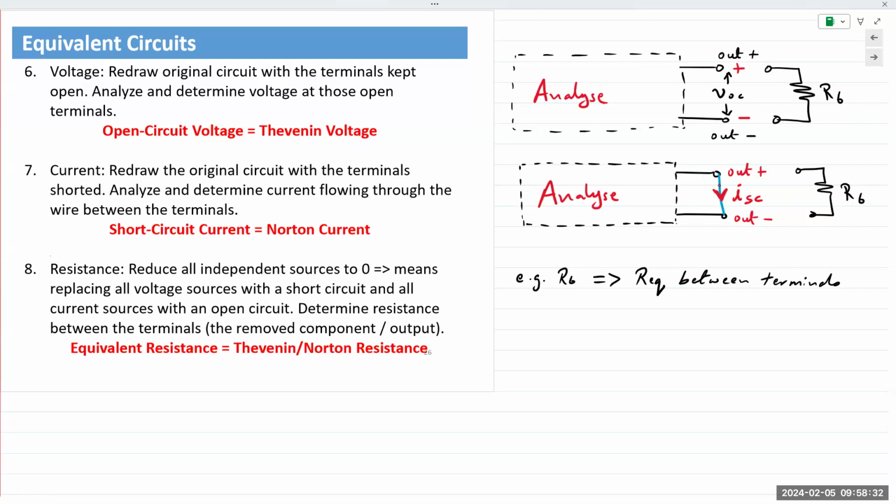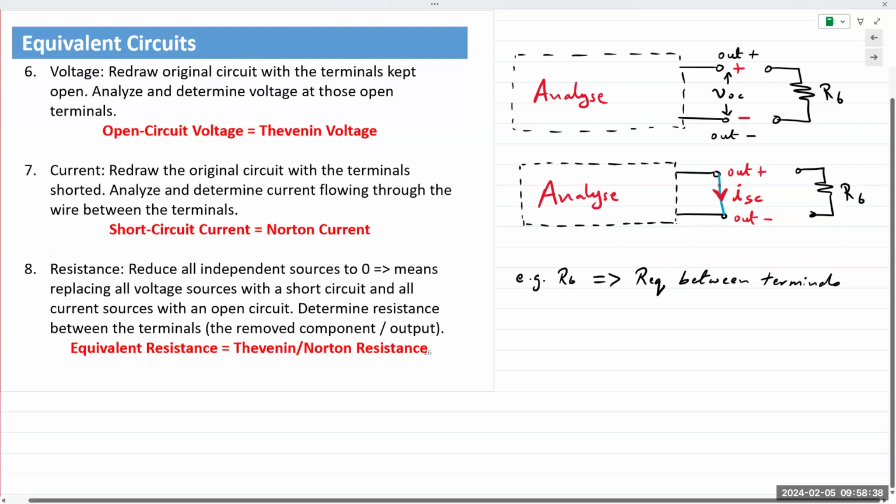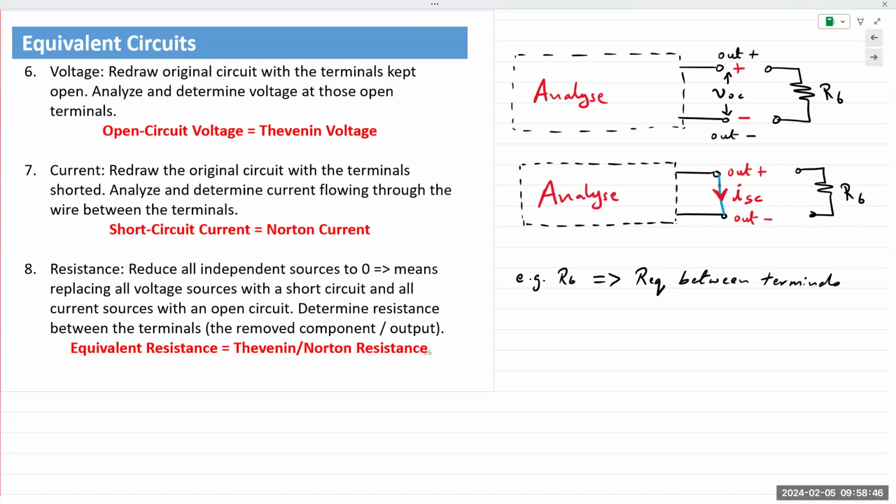Two of them. Anyway, you analyze this circuit twice, once for open circuit voltage, second time for the short circuit current. Open circuit voltage is a Thevenin voltage, short circuit current is your Norton current. And then you can verify your answer by applying Ohm's law between the three terminals. Each circuit is different. Okay, a simple short between those terminals can change the circuit drastically. Okay, and we'll look at examples on Wednesday, and then of course it'll start making more sense.